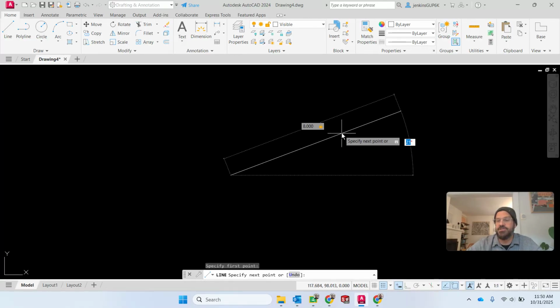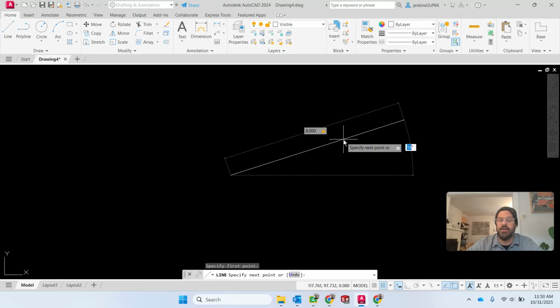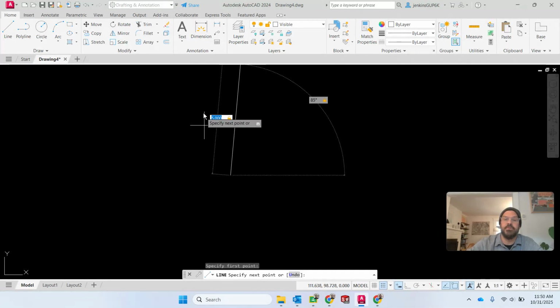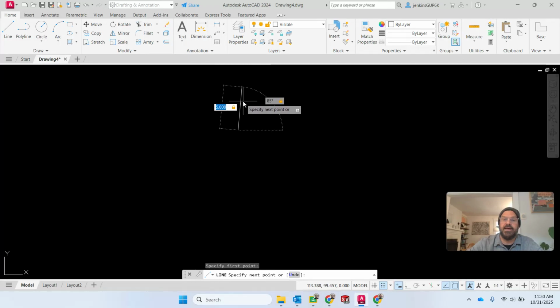And now I'm just adjusting the angle that I want it to be. If I went back over here, I could make it smaller. I could make it 5. Alternatively, I'm just tapping back and forth. I could say I want it to be an 85-degree angle, tab. And now it's locked into 85 degrees.